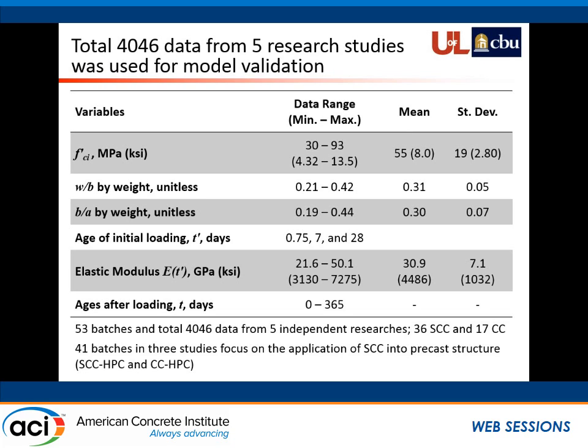The mean value is 555 when we apply the creep loading. And this is the water-binder ratio and binder-aggregate ratio. And then 0.75 is the day when creep loading is applied, which simulates when we release the pre-stress strands, and 7 days and 20 days.